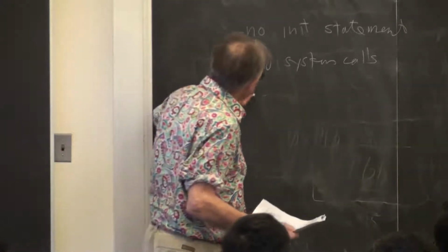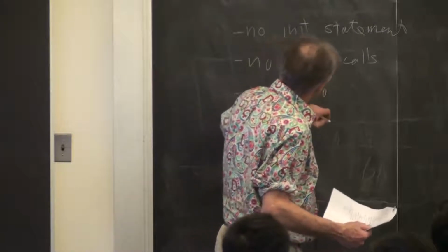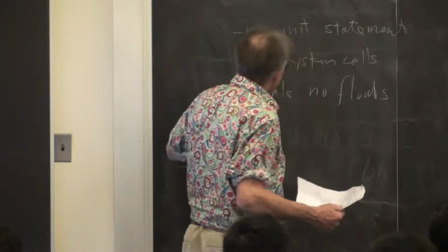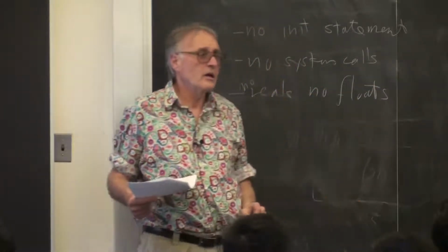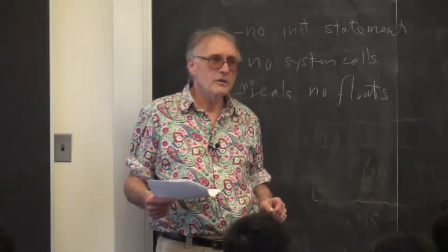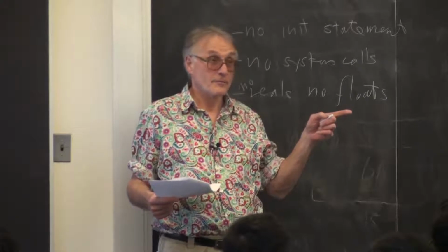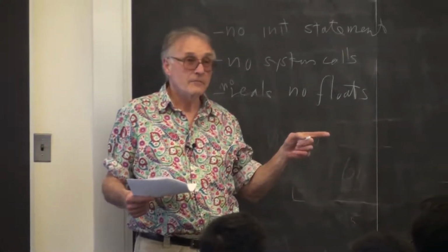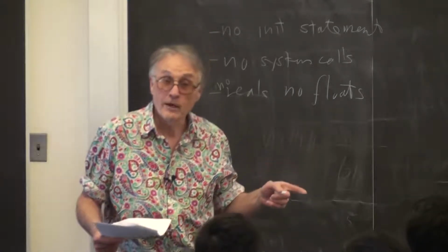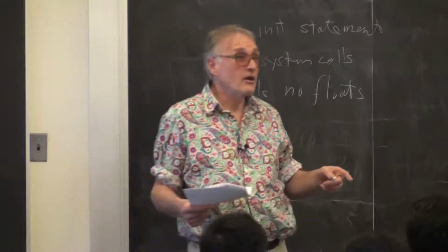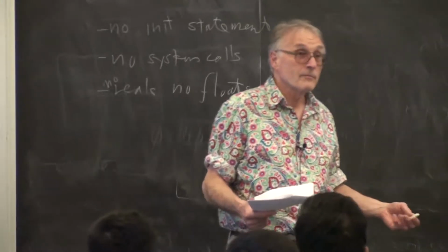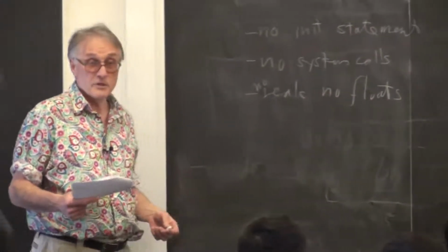There are no floats, no reals. In fact, I would call this a very untyped language. You have one type, a register. It holds bits. You can do anything you want with those bits. You can call them a float if you write a floating adder. You can call them a fixed point number if you write a fixed point multiplier. You can call them anything you like, but it's just a pile of bits.